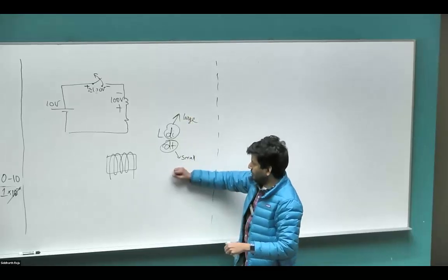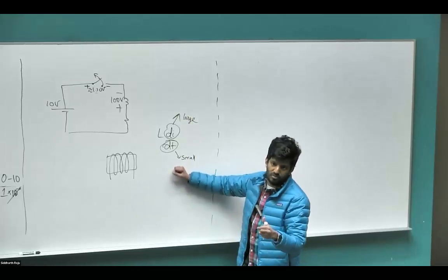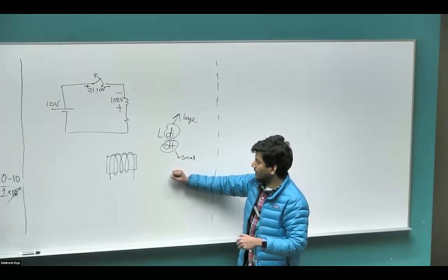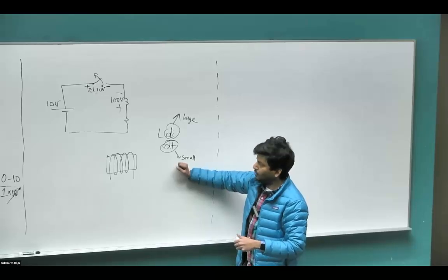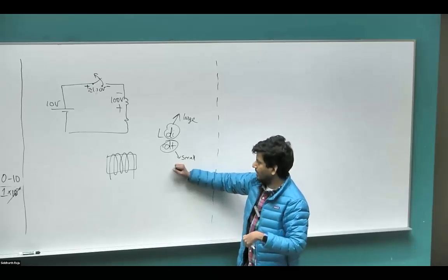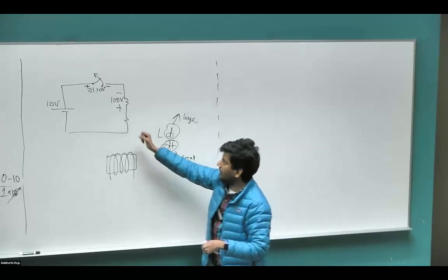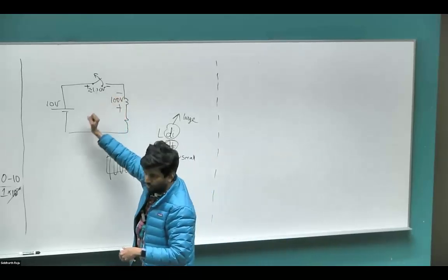And this would typically be the case when we have semiconductor switches, which can operate at like 1 microsecond, or if you have gallium nitride switches, wide band gap devices that can go 50 nanoseconds at very high currents. So the dV by dt would be enormously large, and that would break down any kind of device that you have here. So what is the solution?